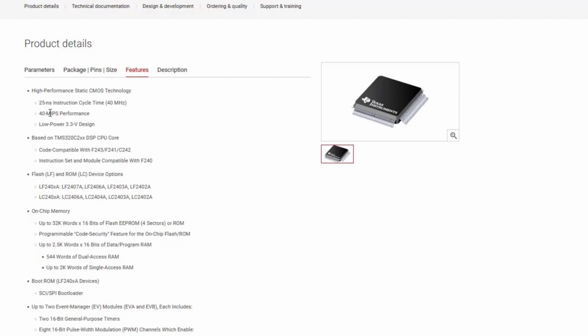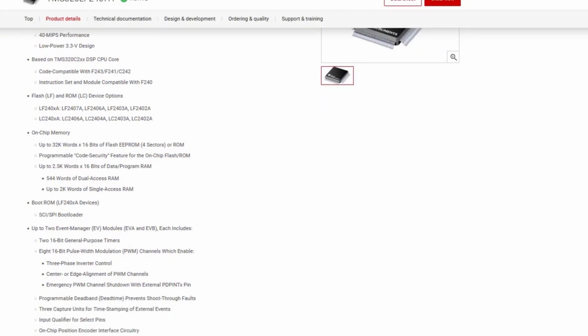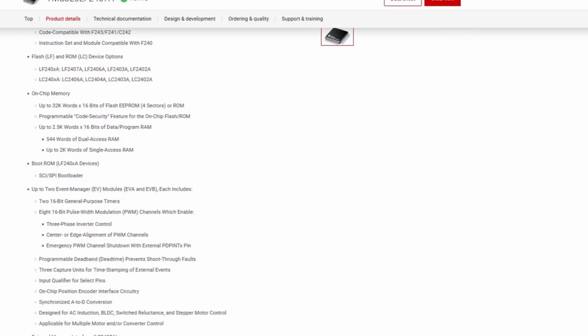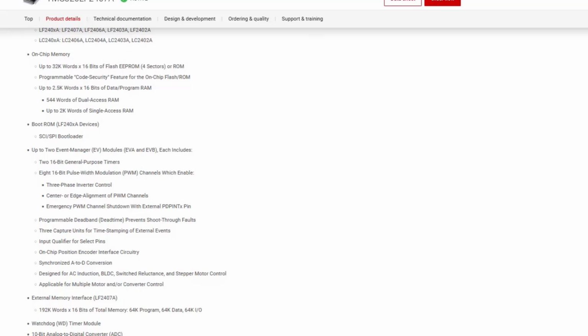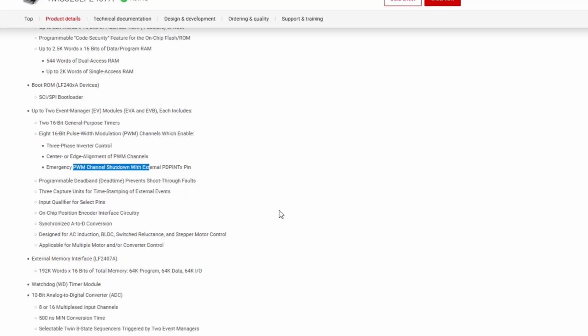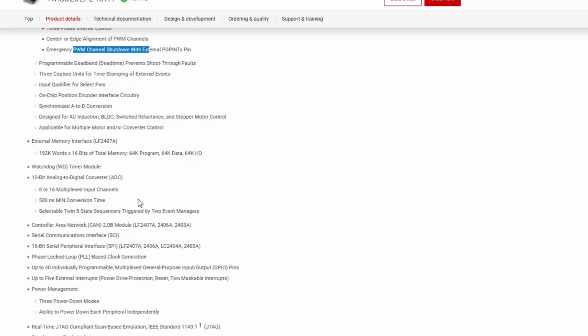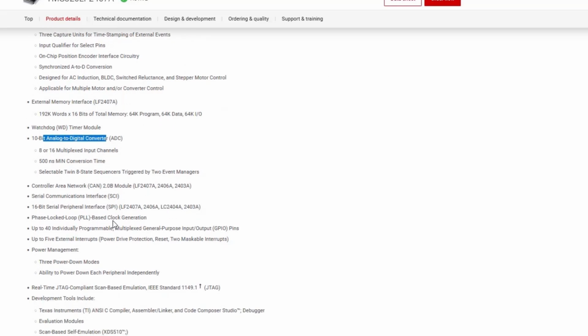This DSP controller offers 40 million instructions per second performance. This high processing speed of the CPU allows users to compute parameters in real time, rather than look up approximations from tables stored in memory. This fast performance is well suited for processing control parameters in applications such as notch filters or sensorless motor control algorithms, where a large amount of calculations must be computed quickly.